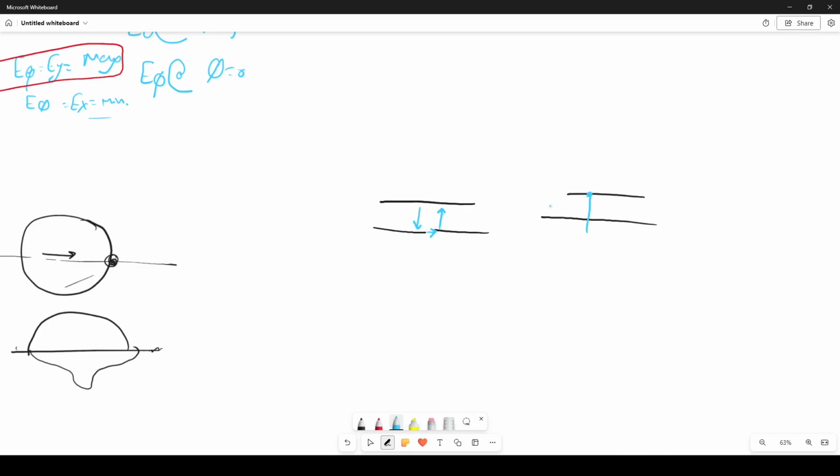Okay, in some cases here I introduce a piece of metal. It forces the field itself to be normal to this, right? Because this is a piece of metal, and we know that for any piece of metal, any PEC, the fields must be normal to the surface. This is the boundary condition of the metal or the PEC, right?